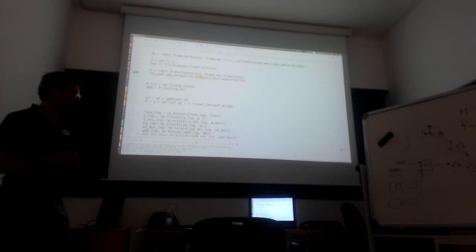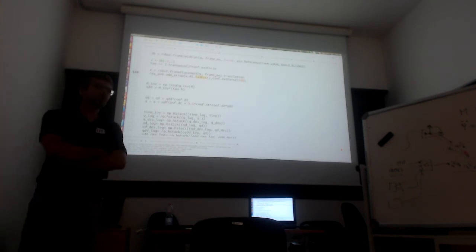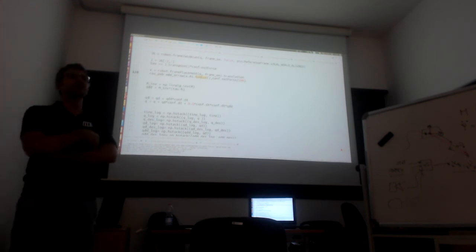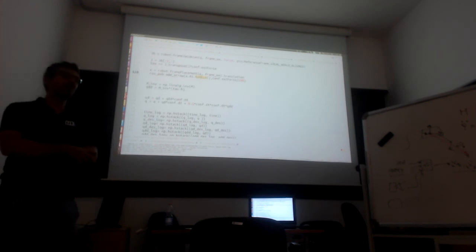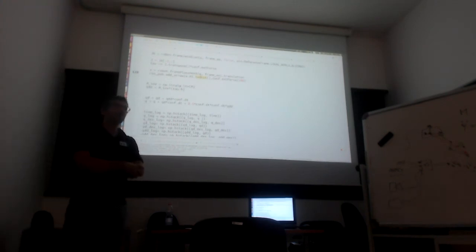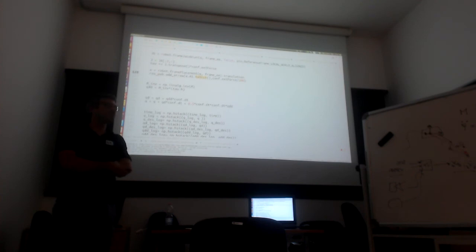On the other hand, we also had the backlash problem that can be mitigated through a good mechanical design, and also the dead band that can be inverted in case of hydraulic actuators or electrical power converters, power drivers for the electrical motors.